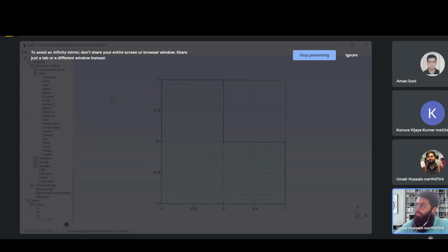So in all geometry options here, I had my element size vector also as one. Before I changed it, it was one. So there, my mesh would have roughly the size of around one. When I had triangular meshes, it was actually exactly equal to one.